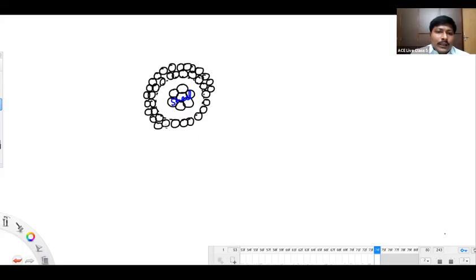So the outer strands are aluminum only. All these strands, whatever I am showing here, are aluminum. Just listen to the words. These are aluminum and internal will be steel. In between these two, the steel layers and aluminum layers, we are filling with some low-grade insulator material. It's a filler material we call sometimes. We call it a filler material.